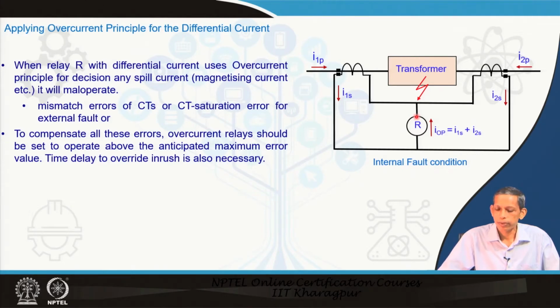If the fault is external with a very large amount of current, along with a CT ratio mismatch, then we know from the CT performance study that the CT may saturate, and thereby the corresponding current may be substantially low. So, for an external fault, if any of the CTs saturate, then even though it is an external fault, differential current will flow at that time also.